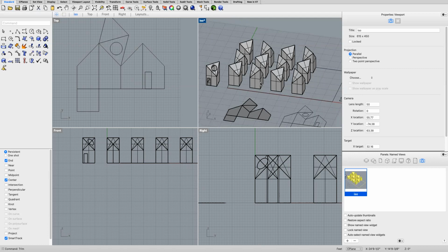Right now we actually have a little bit, but notice it only really happens in the evenings as we get closer to summer, maybe a little bit in the mornings too, but mostly the sun is over here, right? So general rule for skylights, north facing slopes. You'll still get some direct light in, but you want to try to minimize that.